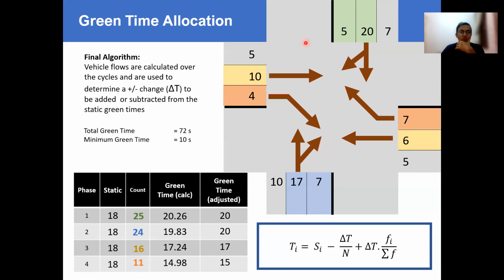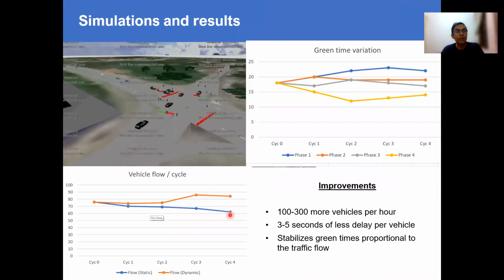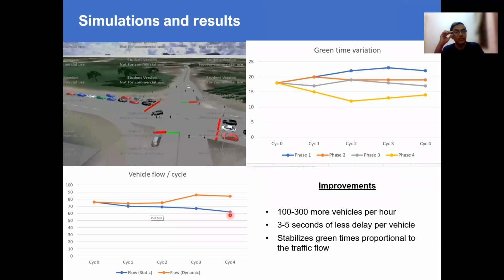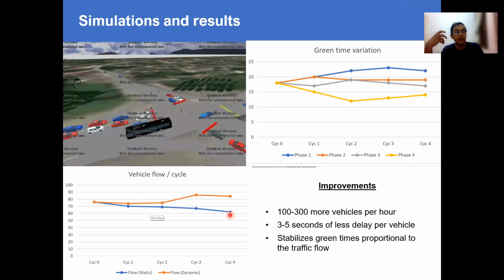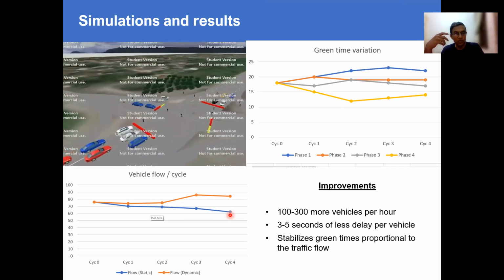So the last column is actually once you round it up to seconds, you don't want to go below 1 second, let's say 500 milliseconds or half a second, because you're dealing with vehicles. They're a little slow to start and stop and all that. So therefore, in terms of seconds, we measure everything. This is the simulation on SUMO, which is actually not only a simulation of the vehicle flow, but also controls traffic.